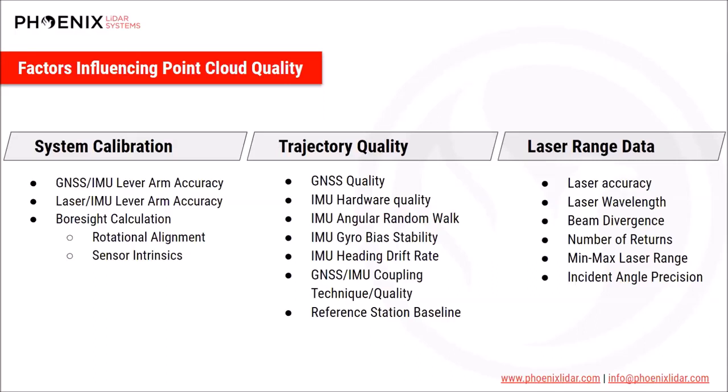All of these are very varied between different lasers and are important to understand and put in the back of your head while putting all of these multiple pieces of the puzzle together to understand what sort of quality your point cloud will have and what sort of processes you will need to go through to create survey grade point cloud quality.